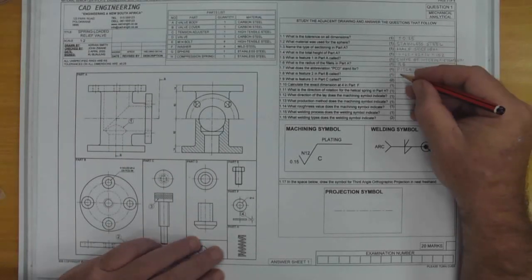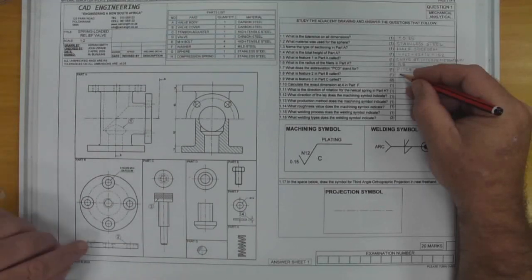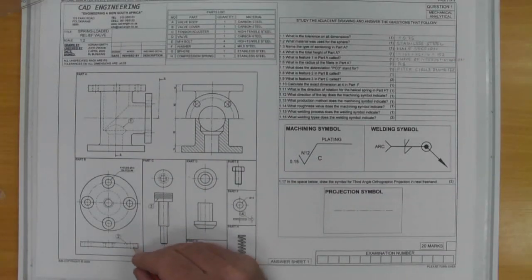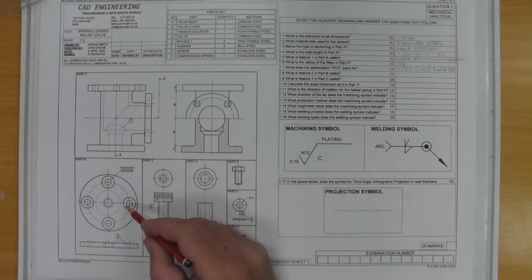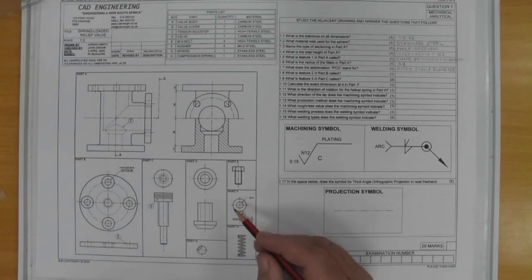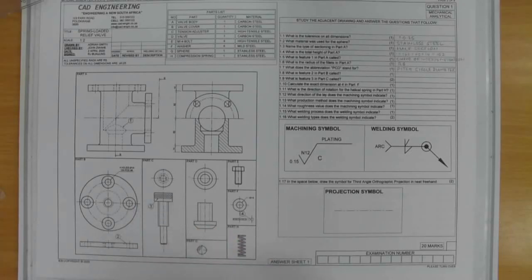What is the feature 2 in part B? Here is part B. So this is where they've cut, and the hidden detail is showing that that is slightly below the surface. So when you're putting something down with straight sides, it's implying that maybe your bolt is going to fit a little bit lower on the surface of the shape. Or maybe the washer. Is there a washer? No, a washer could fit in there.